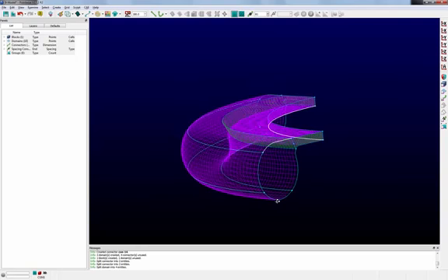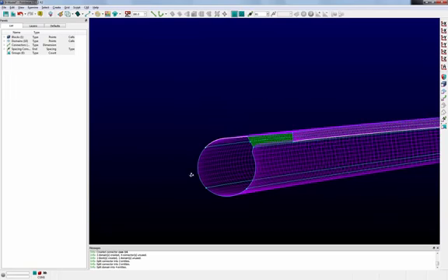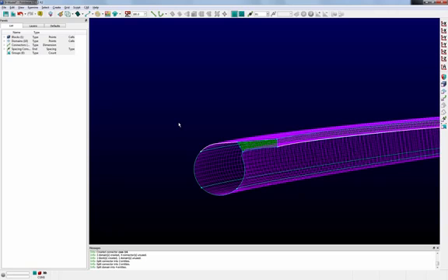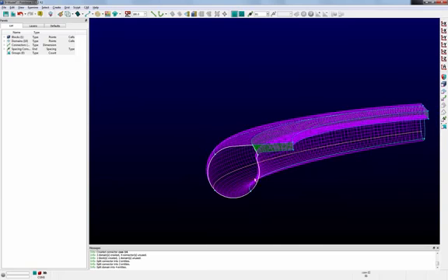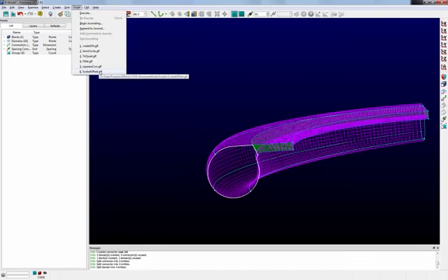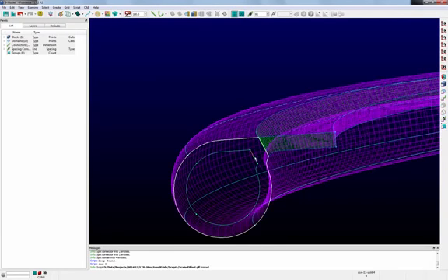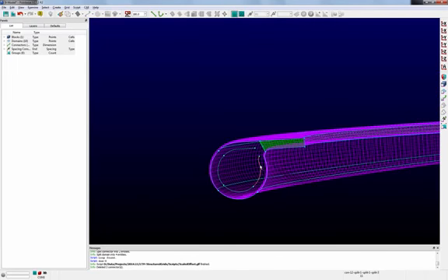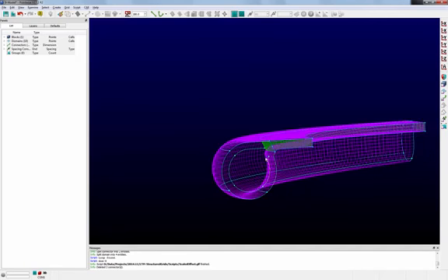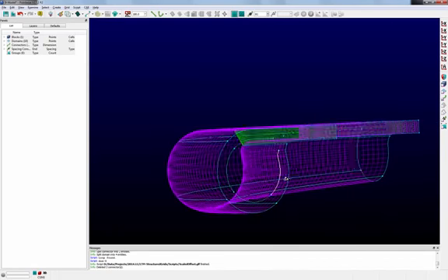So the next thing that we want to do is create that boundary layer block. What we can do is, again, use a script to help create that. You can try extruding this, but because it's an odd shape, it's a little easier for me to just generate by hand. So we're going to highlight this and run this other script that I've written called scaled offset. This has a hard-coded parameter that you can change that's currently set to 0.75, and it just scales the loop of connectors that you've passed to it by 0.75, with respect to the centroid. So it's just going to scale that and create these new connectors right there in the middle.